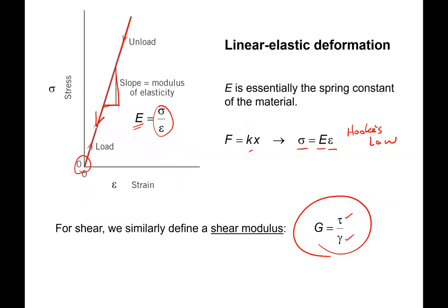We're going to be looking at linear elastic deformation. First, what we mean by elastic is just that when we load a sample up, so this is my stress strain data, say taken on that tensile machine, I could, instead of running this to failure like you saw, stop after some load, some stress value, and unload, and we would end up back at 0. That's the definition of elastic. We would return to our original shape. There's no permanent deformation in this case.